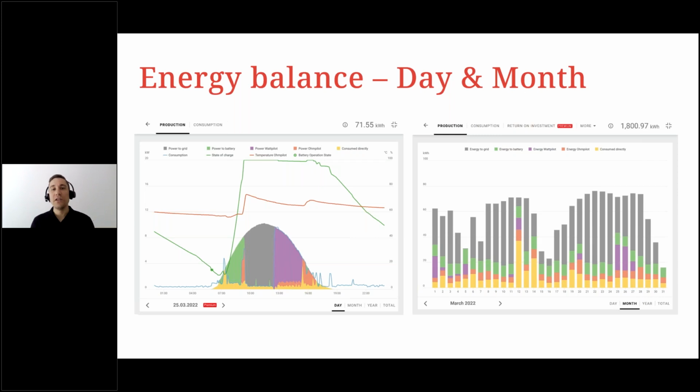With our single to three phase switching, we can see here that the sun curve can be directly followed, and therefore only PV surplus energy is fed into the electric vehicle. You can make sure that each and every amp that comes from the PV system can be charged into your electric vehicle, so that you get very good surplus energy usage and very good own consumption rates. More or less, you can compare it a little bit to our heat solution, the Fronius Ohmpilot. It does basically the same on another technical basis, but overall you can see that for own consumption, these processes are very efficient.